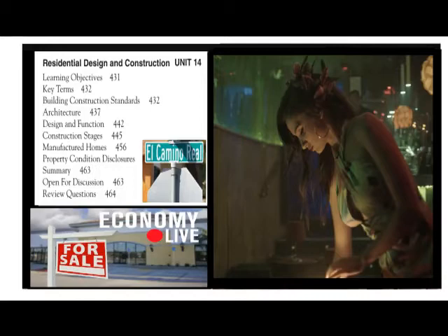The floor of the house also may be concrete, poured either at the same time as the foundation walls or after. More commonly used is the wood floor on concrete foundation walls, usually plywood panels over wood beams called girders and joists. This design leaves a crawl space beneath the home for ventilation and protection against termites. It is illustrated in Figure 14.3. Instead of continuous concrete foundation walls, some older homes have concrete or stone supports called footings.